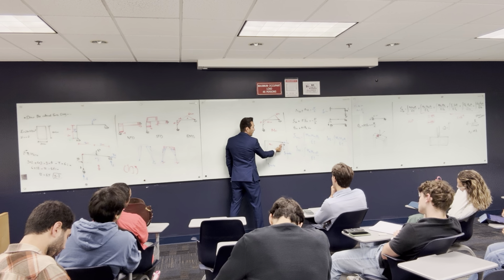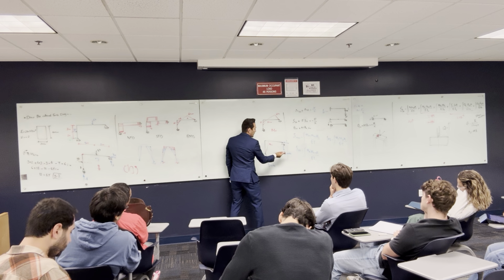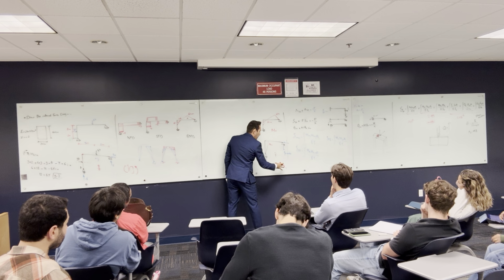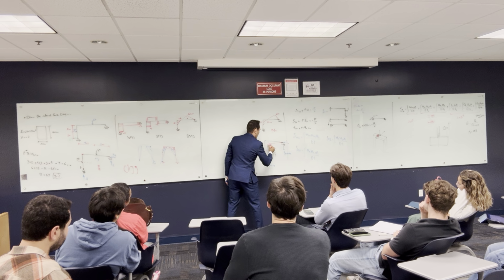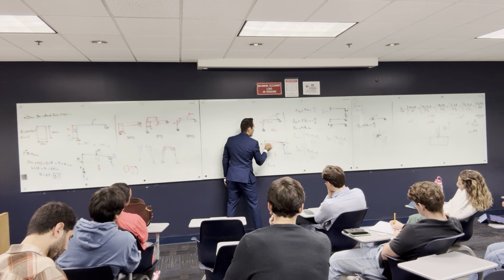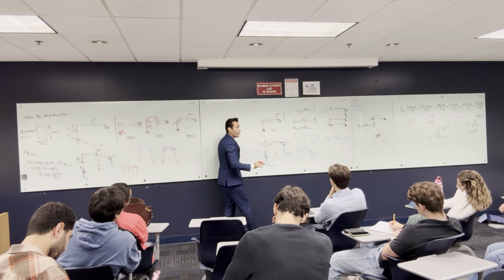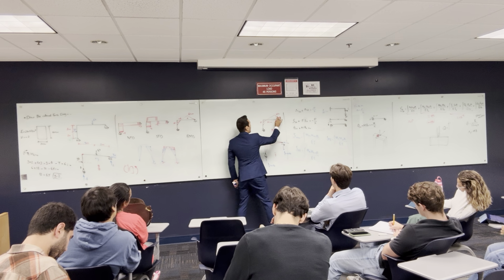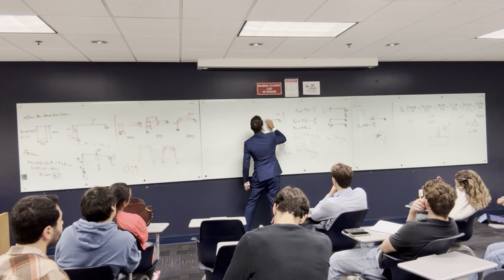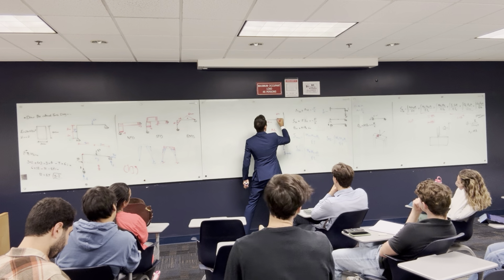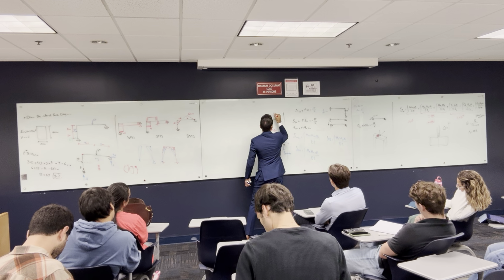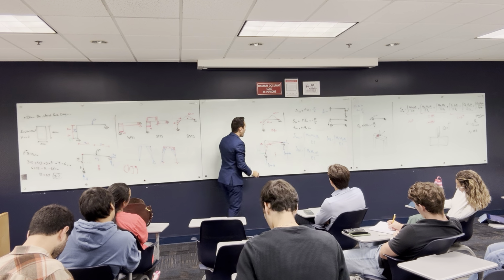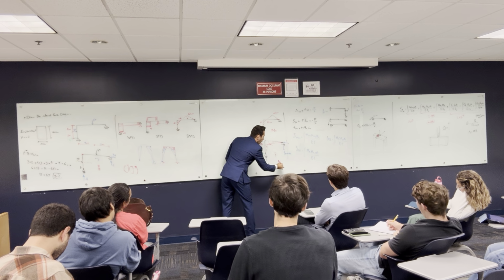How about the moment here? It's a hinge, the moment is 0. Here is 0.67 multiplied by 6, so it's going to be equal to 4 ton meter. That is negative and negative. By the way, the sign is very important. And let me draw this right because the 6 is in the middle. So right now I have M0 and I have M1.